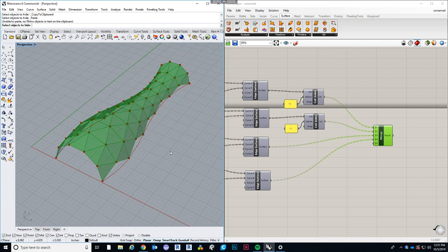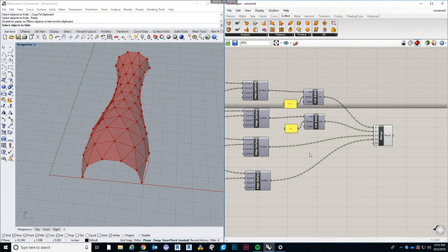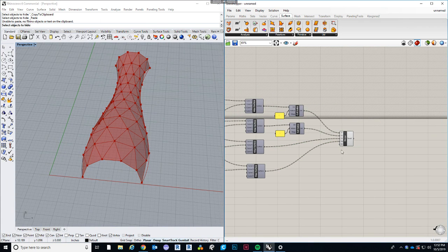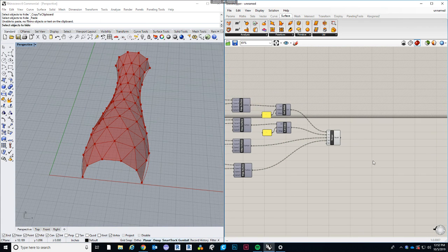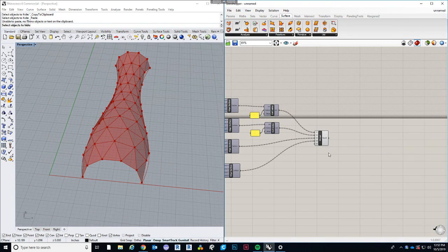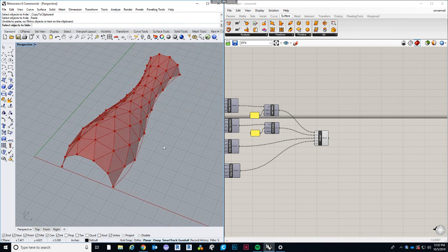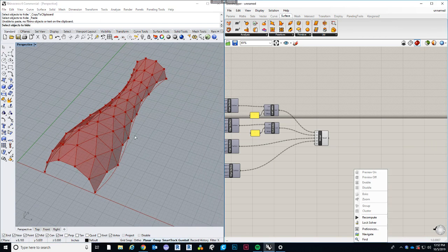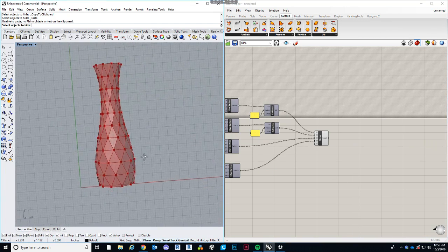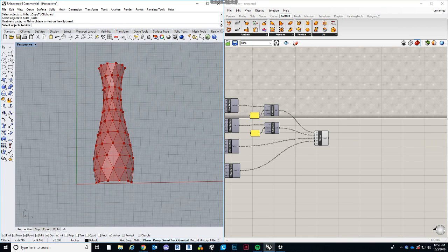Now we can use those triangulated panels just like we've been doing in previous classes with the attractor scripts or transformations. I think in what I showed you before, I was using a point attractor. This time we'll use a curve attractor. So if we go back to Rhino and just draw a curve in the middle of this, like so.